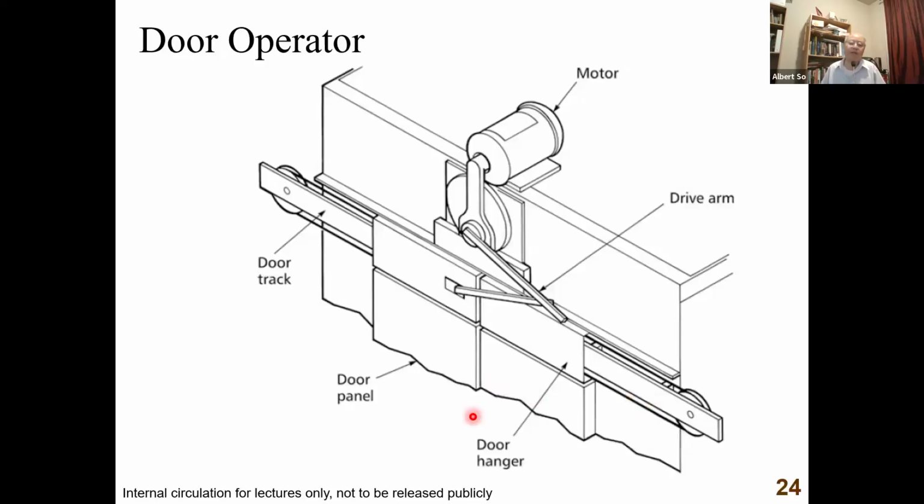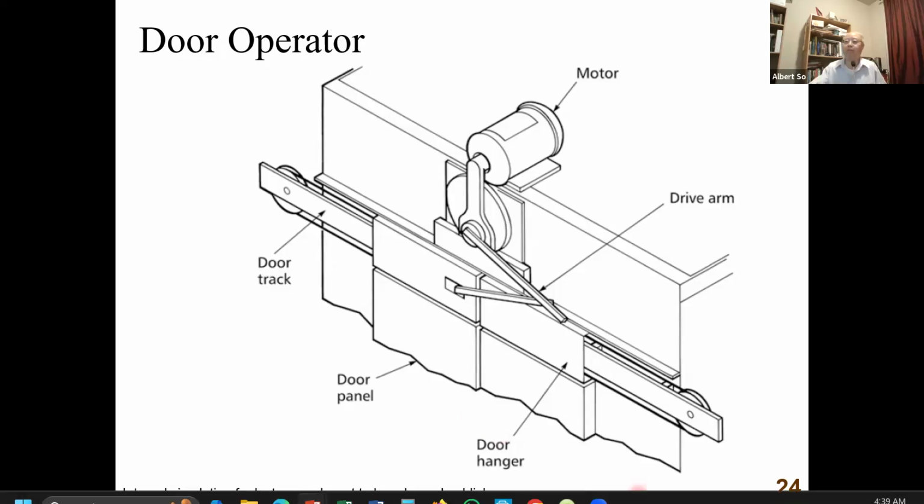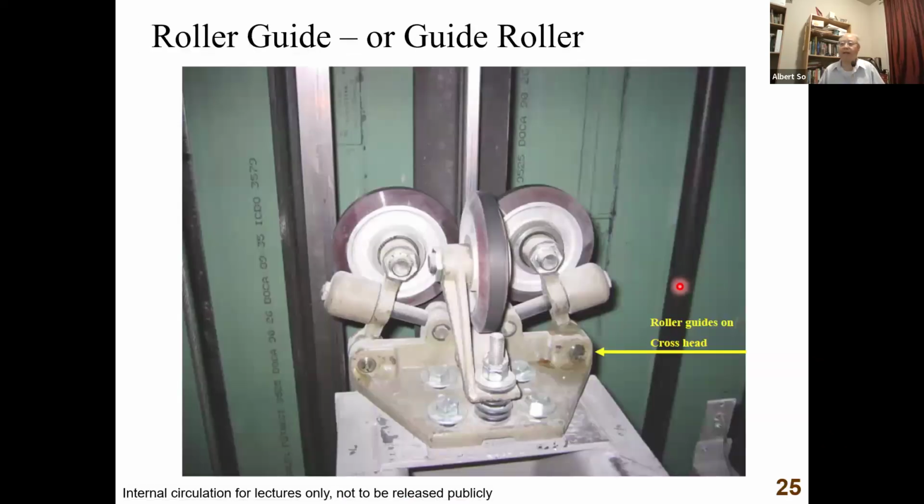The mechanical system is simple. There's a rope system with a small counterweight. So when the landing doors are open, the rope arrangement will lift up the small weight, not counterweight, a small weight. Okay, small weight. So if the car is not at the landing, then that weight will try to pull the rope down and then close the landing doors. It's a passive mechanical system. Passive.